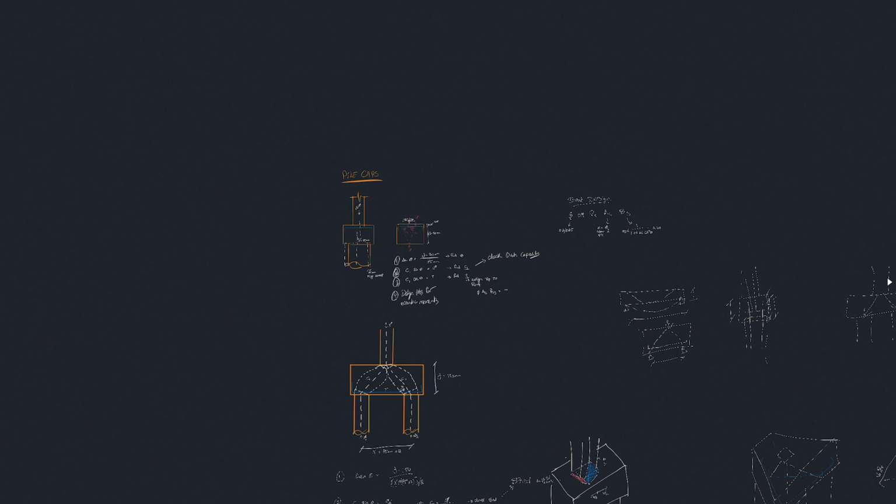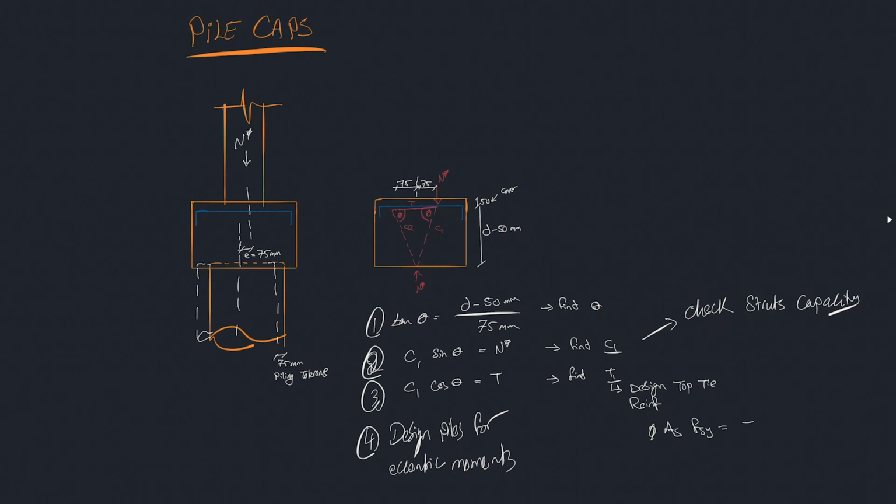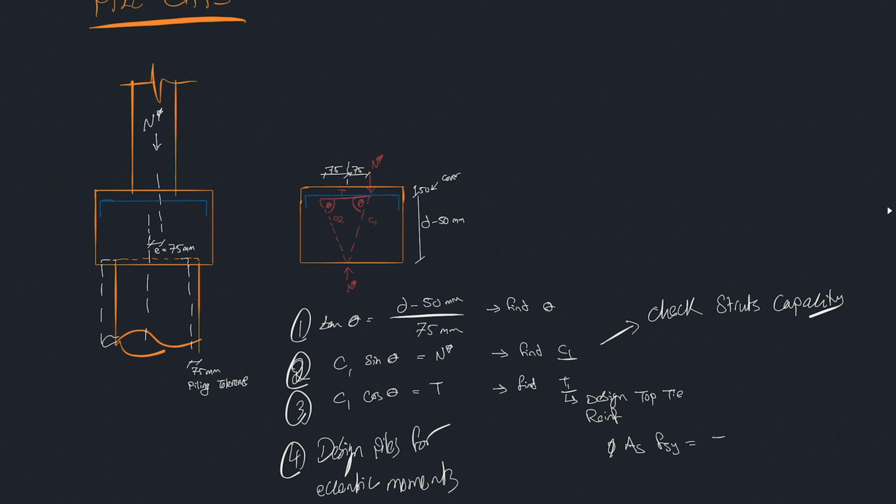So let's start looking at our single pile cap. We already explored the design theory behind it: the first design rule for designing a single pile cap is to get sufficient depth to actually develop your bars. Whether you have tension, you need the full tension development length, or whether it's in compression, you need a full compression development length. If you're going to cog your bars, then you only need half of that. And then the second design is to take the eccentricity due to tolerance in piling.